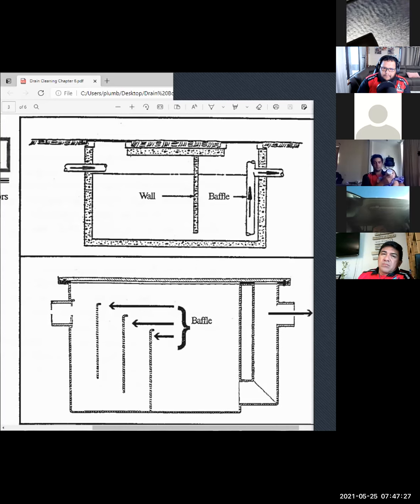And you can always encourage the guy to say, hey, there's a lot of buildup in here. Talk to your grease trap pumper and see where your mantle should be on this thing. I think you're right there at your maximum. That's a safe out. It shows you're knowledgeable, and it isn't your kuleana. Our job is to make the thing drain. If the exit's clear and the entrance is clear but it's not draining, that very bottom baffle could be stopped up, which is very seldom going to happen. But that's how you have to have solutions. You have to understand the principle and the way they operate.